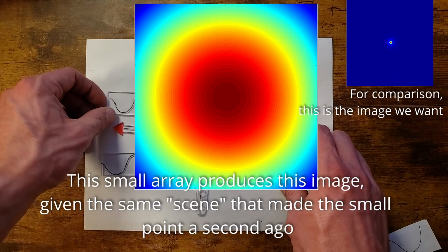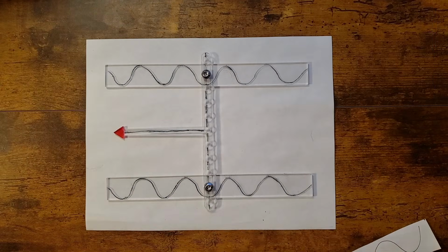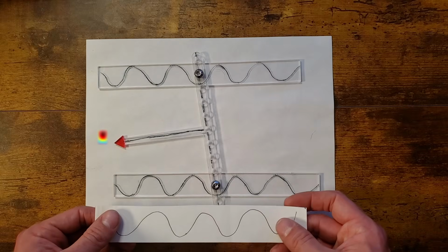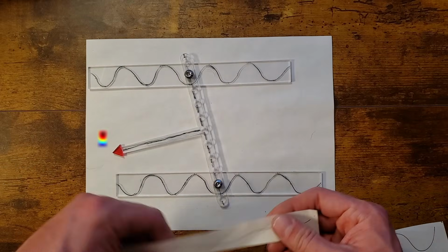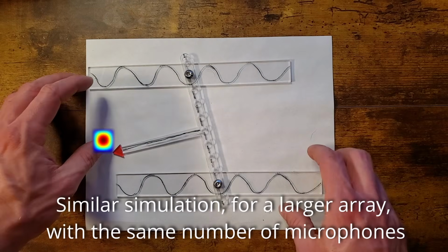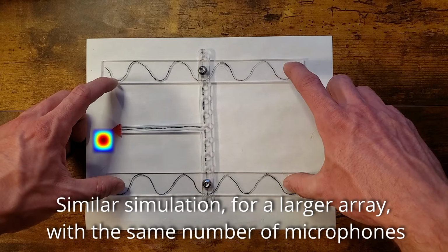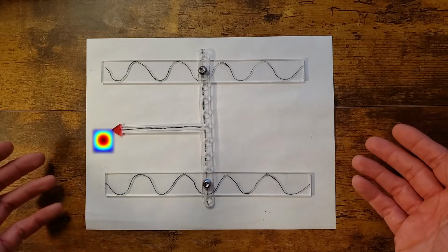If we space out the microphones a bit, though, we measure right in front of them, we get full strength, we move them over just a little bit, a few pixels, and we're down to maybe 1. Move them over a tiny bit more, and we're all the way down to 0. So the size of the spot in the image has shrunk. It's a sharper image. It's less blurry. This is significant. This tells us that the size of the array, relative to the wavelength, is what sets how sharp or blurry the image is.